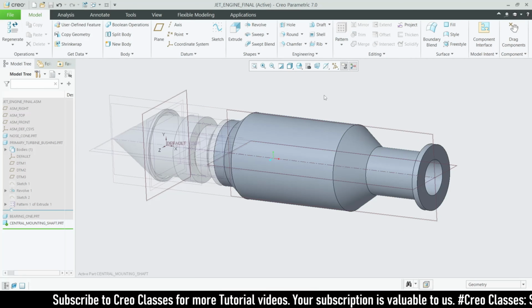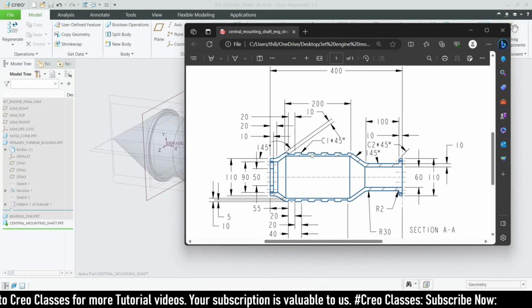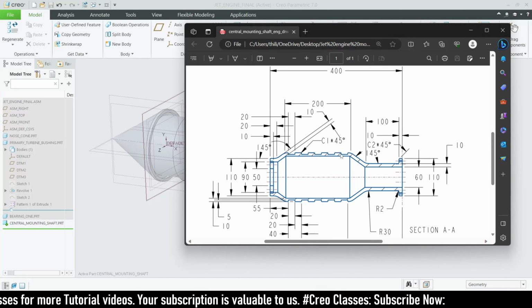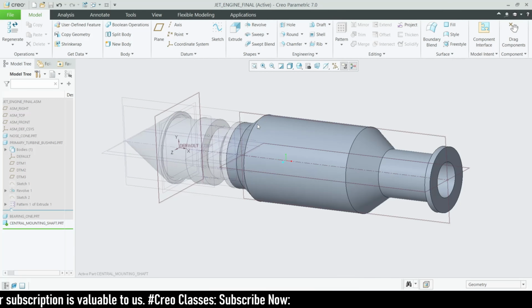Then we need to create one more feature, like we have forgotten to create these curved edges. So we need to create this. We need to go for the revolve again. We need to revolve for this part.